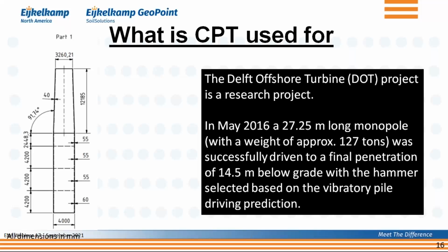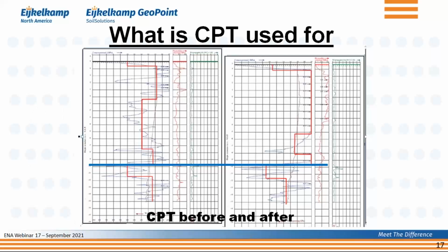And you can see here how long that pile was, about 27 meters, so about 90 feet or something like that. And it had a diameter of about 4 meters, so about 13 feet or something like that. And the beauty was, after that pile was put in the ground, a CPT was done. That was then compared with the CPT beforehand.